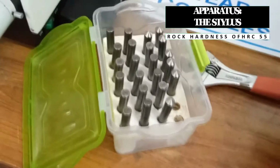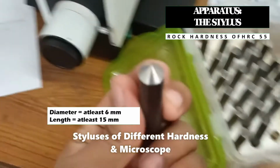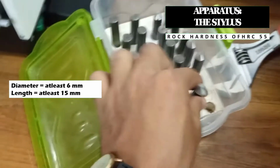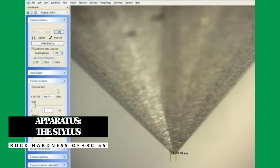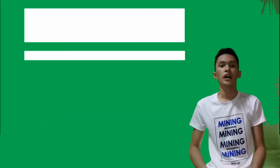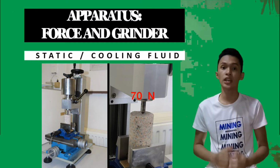The diameter of the stylus should be at least 6 mm and its length shall be such that the visible part of the stylus between the pin shank guide and rock surface during a test is at least 15 mm. The tip of a stylus shall have a conical angle of 90 degrees. A worn stylus should be resharpened and the tip angle checked under a microscope before use in a further test. The static force acting on the stylus should be 70 Newton.